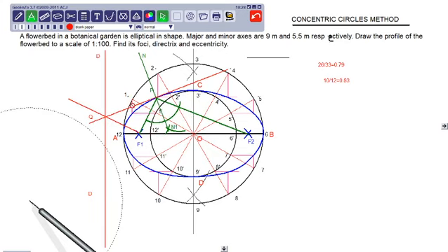So at point 1 I have drawn a vertical, at point 1 dash I have drawn a horizontal, and they are bisecting in this position. They are cutting each other in this position. Similarly at 2 I have drawn a vertical and at 2 dash a horizontal, and where they are cutting is the point. So everywhere I have done this, and at A you draw a horizontal, draw a vertical, it is the same point.